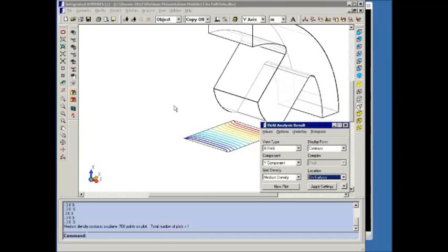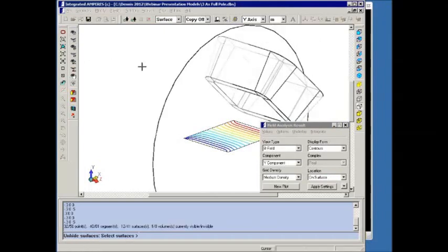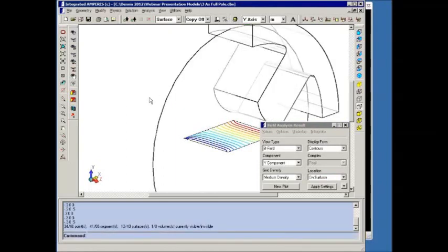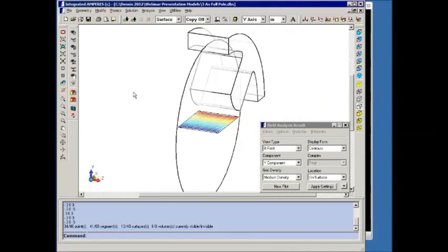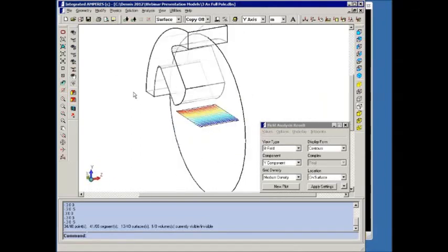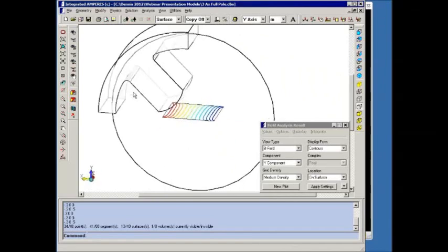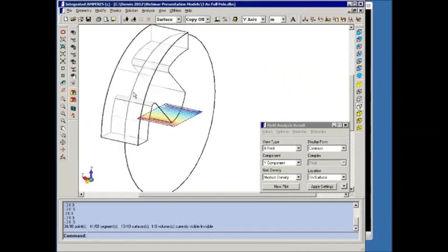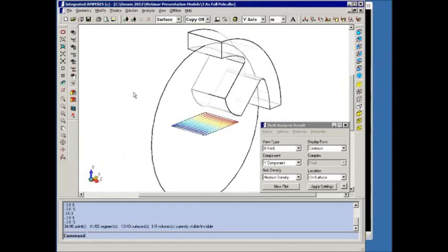to create reference geometry. So in fact here, I'm going to show you that in this model we have an extra surface defined. We have a circular surface which I've hidden, and now I'll display it. This circular surface has been constructed so that it passes right through the middle of the pole, and also it covers the airspace between the poles. And that does no harm because we haven't assigned any physical properties to the surface. It's just there for the convenience of plotting.